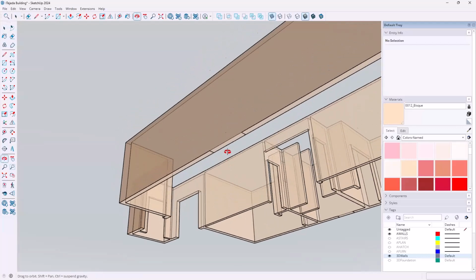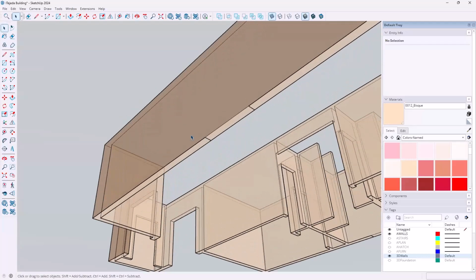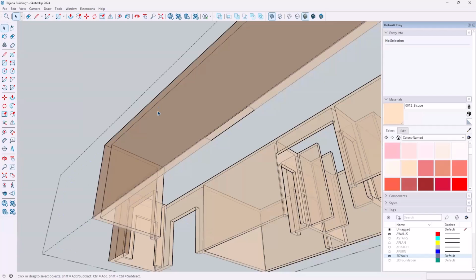And then I'll draw a rectangle from this endpoint here to this endpoint. And then type P for push pull. And again, notice I was not in my group. So let me tap the escape key and tap the space bar. And in this case, it's just easier to go ahead and edit, undo the rectangle and go into my group like that. And then draw the rectangle.